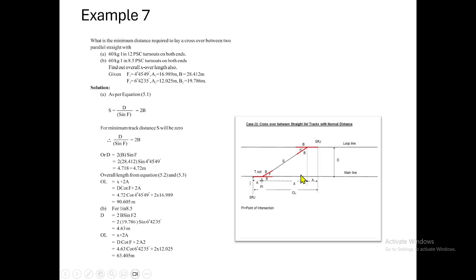However, as per Schedule of Dimensions, the minimum track distance we must ensure is 5.3 meters wherever we do new works. For existing works, I think they have gone with 4.265. But anyway, nowadays the maximum we used to have is only 4.72.